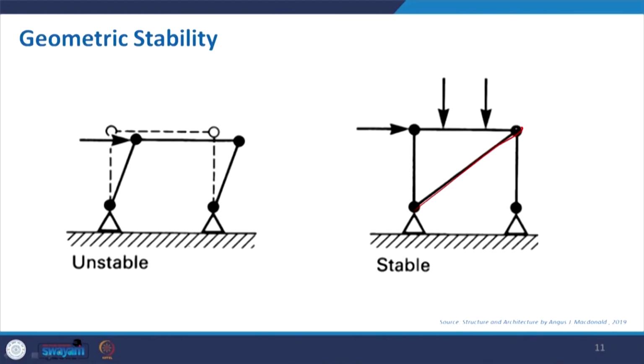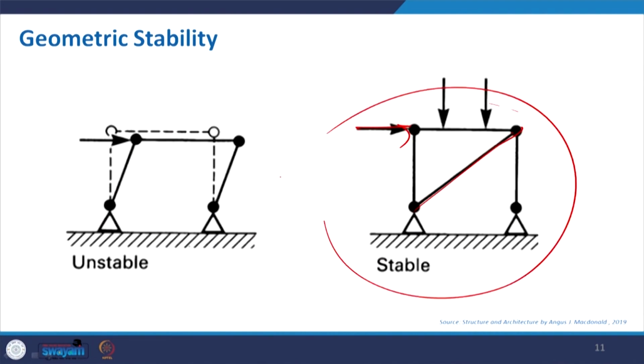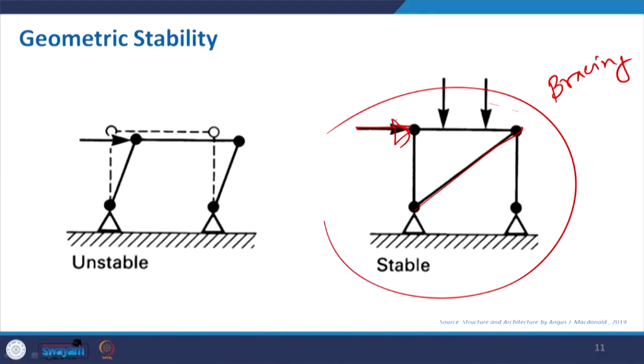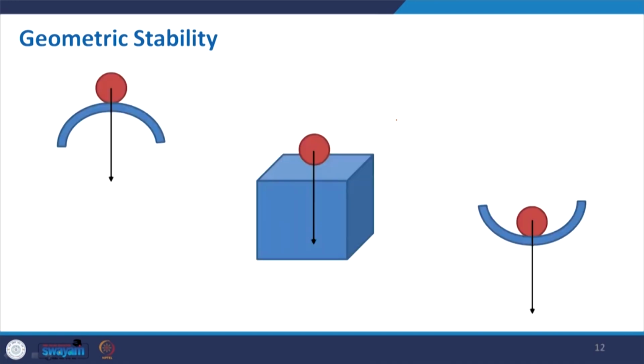Now, this is the same example as I mentioned earlier, it was something like that, and then this is connected. So, that particular arrangement is giving more stability. This kind of arrangement is called bracing. We will be using this bracing term quite often when we discuss high rise structures, because in order to protect from the lateral load, we need such kind of development.